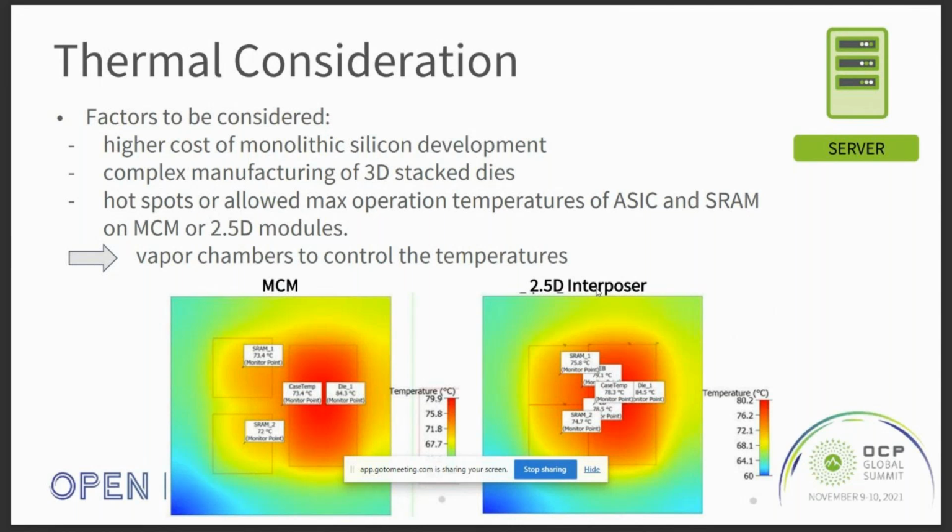If we have the uniform power distribution, and we put this chiplet into a server, I think the junction temperature will not change a lot unless your non-uniform power distribution is very extreme. What I mean is that if all the power is concentrated in a small area, then of course it will be different.